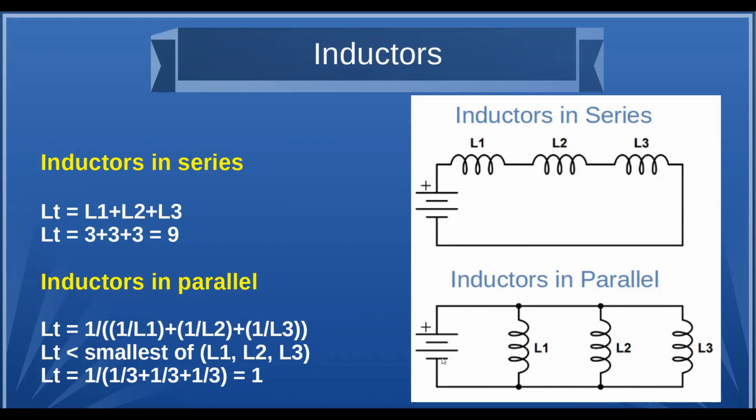So if I go in this direction, I've got a positive voltage and then an opposing voltage. The sum is zero, because I'm going to take this one minus that one. Likewise, if I went around this loop, I've got a voltage this way and a voltage this way. So I'm going with this voltage against this voltage. They add up to zero. Does that make sense?